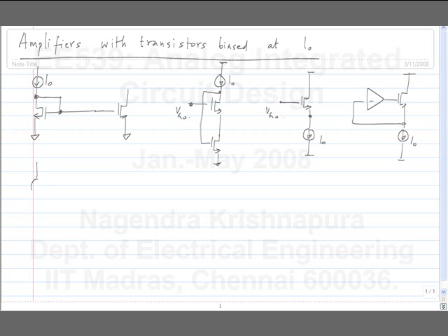So what we want is the VGS here to appear across this transistor for DC, right? And we would like the small signal that we apply, which for now we can assume to be above some lower cutoff frequency, to appear across gate source at those frequencies. So how do we do that?